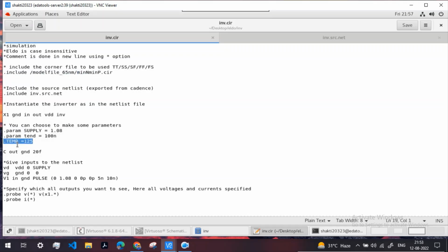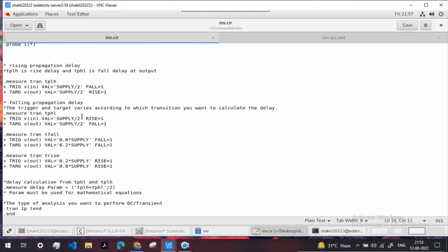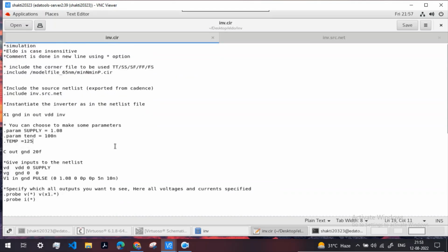stands for temperature. So we have modeled using anything we want, but generally in an actual scenario, we always simulate for the worst case criteria. Suppose we are measuring these delay numbers and basically we are modeling the propagation delay number. So for delay, for the worst case condition, we need to have the PMOS and NMOS both as slow.